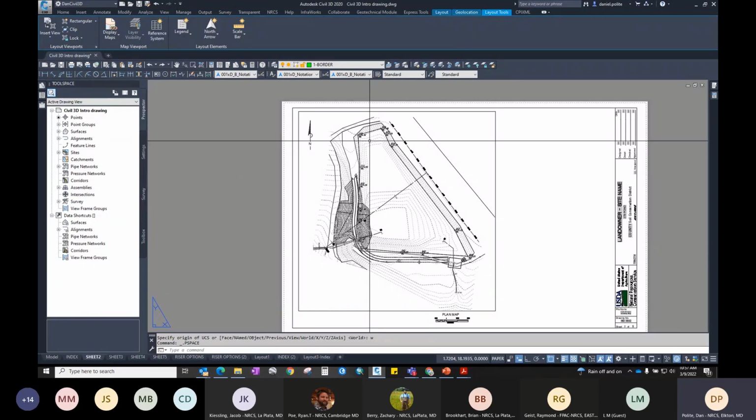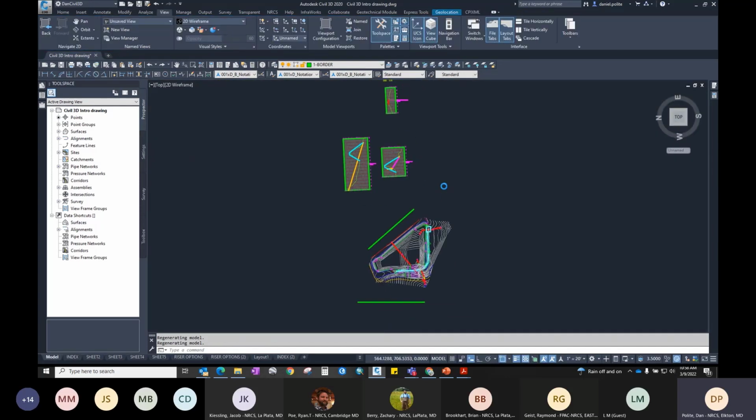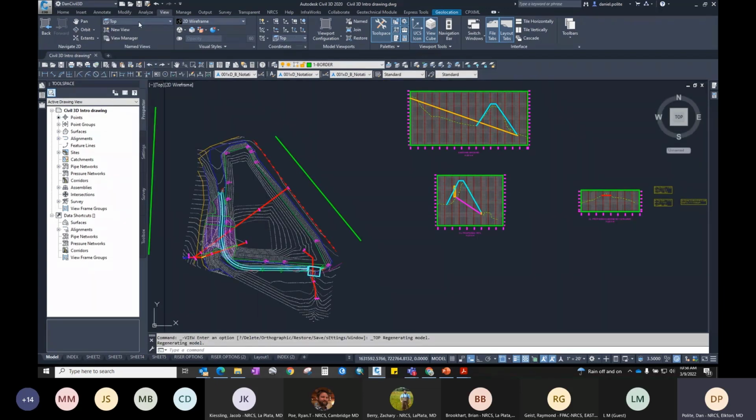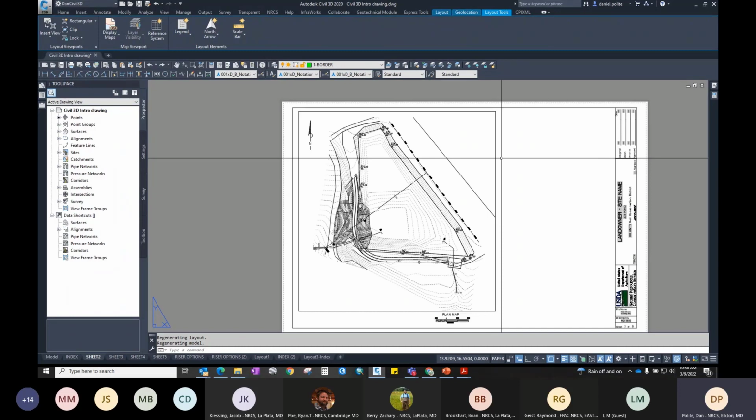In the past, they used to have, I believe it was like DVIEW twist or something, and it would twist the entire screen and it would just get everything all jacked up. So if you need to do any twisting of anything, my recommendation is just going back to the named views that you have here. And then that way in model space, you can adjust any text you have in that viewport and change it that way. That's probably the easiest way to do it. Personally, that's what I would recommend doing.